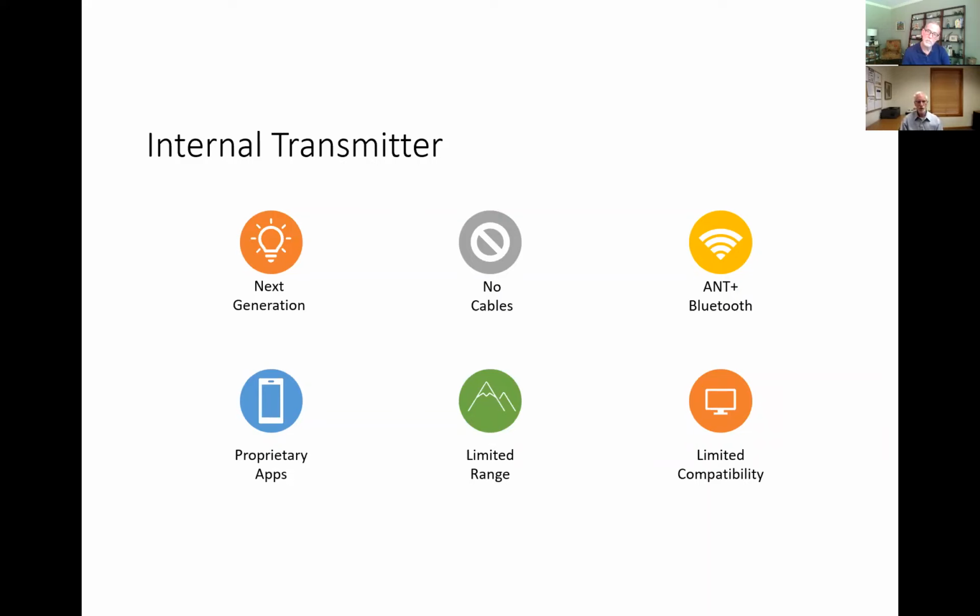But if you're going with somebody who has a Bluetooth transmitter built into their device, each one of them has their own app. And I cannot send data from one manufacturer, like an Amada thickness gauge or a force gauge, to the app on a Starrett. So you have to be cognizant of what you're trying to accomplish and what tools you have, and make sure you've got an app that can read all the devices that you need at that particular workstation. Otherwise, you're going to have multiple apps open on your device.